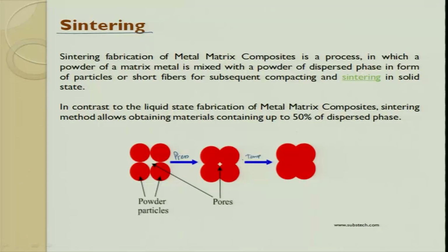If I do not want to apply temperature, naturally our pressures go extremely high. That is why people do hot pressing, cold pressing, and hydrostatic pressing; all these things are tried. If you can do both, that is good. If you have only one parameter to work with because of some constraints in the material, then the other one, if it is not there, the pressures have to go phenomenally high or the temperatures have to go phenomenally high. So, you have to think of an equipment for it.